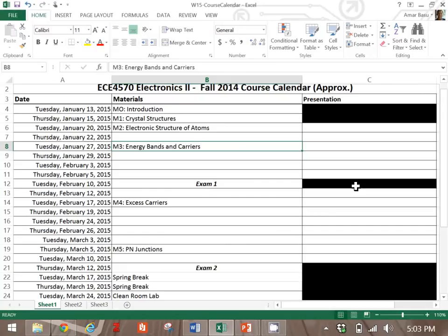So when we're talking about moving charge, we have to think about what type of charges we have. There are two types of carriers. One has a negative charge, that's called the electron, and one has a positive charge, that's a hole. Both of these types of carriers can move through a semiconductor material, and when they move, they create electricity. Okay? So we'll talk about those two types of carriers. We'll talk about the ways that those carriers can move.